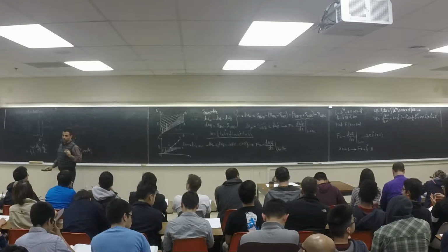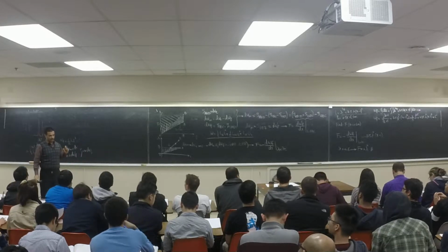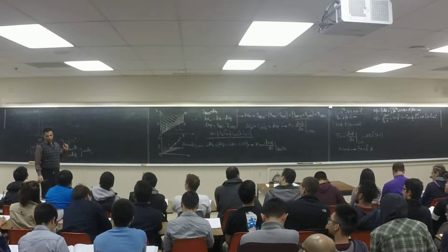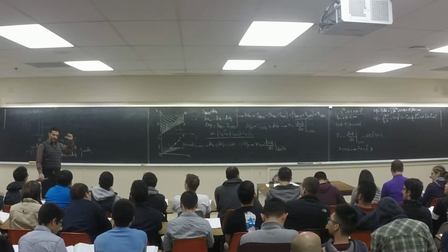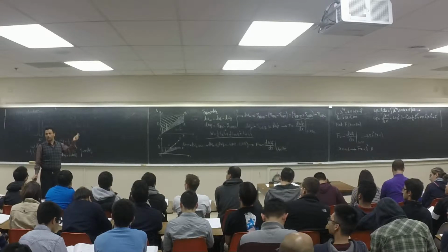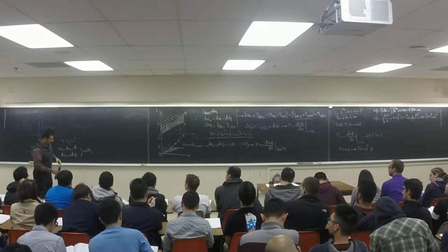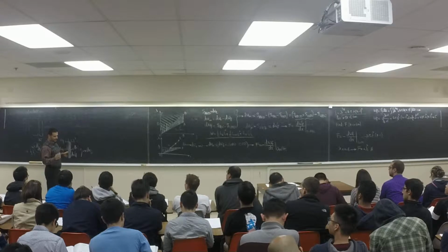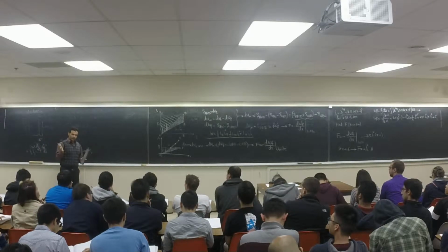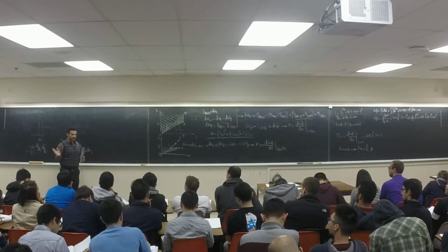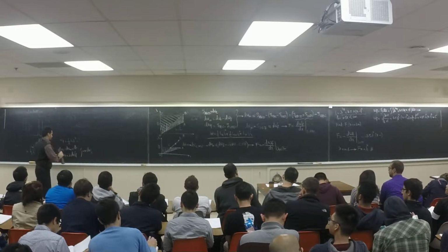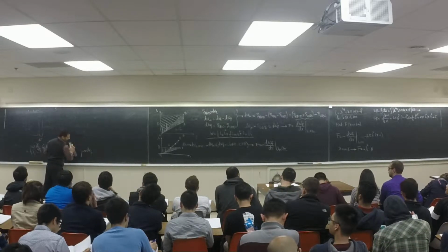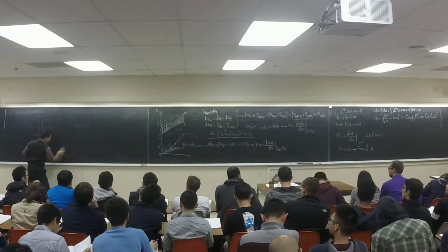So if you hear in a question something like slow moving or fast moving, it just relates to the constant flux and constant current. Very simple. It doesn't mean slow moving. Either it's a constant current or it's a constant flux. So basically, figure out which equation you should use for the calculation of the force, the energy or co-energy.